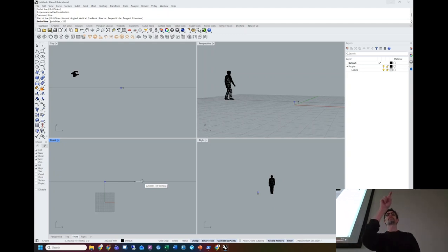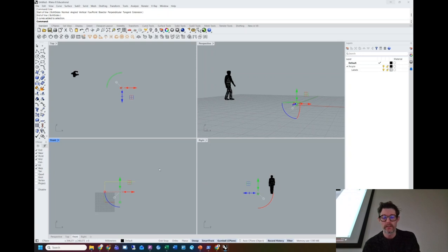I've clicked the first point, I've typed in exactly how long I want that line to be, and it's given me exactly the same thing here, which is the black part of the line is 220 millimeters long. The white part is just telling me the direction I'm going in. I don't actually have to drag the mouse further than the line. I could drag it just a little bit less. And then I click. And now I've got the outline of the first stair.